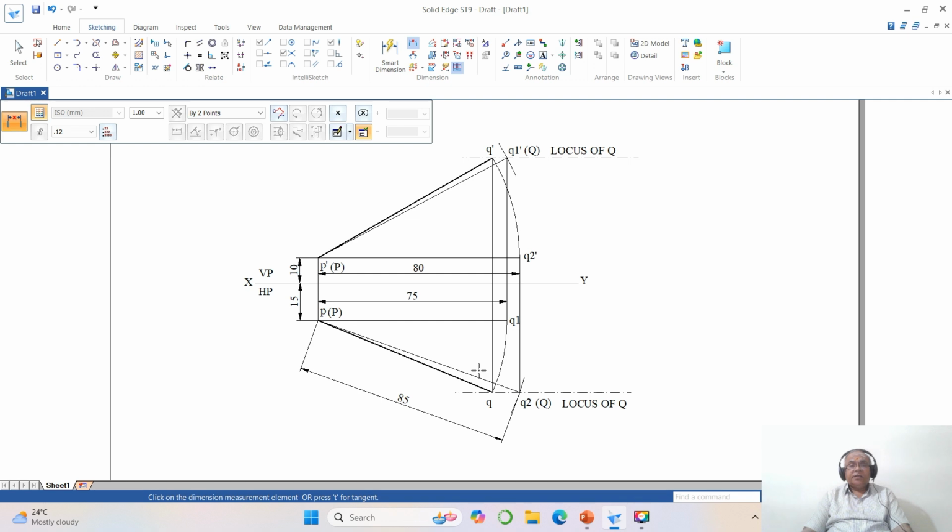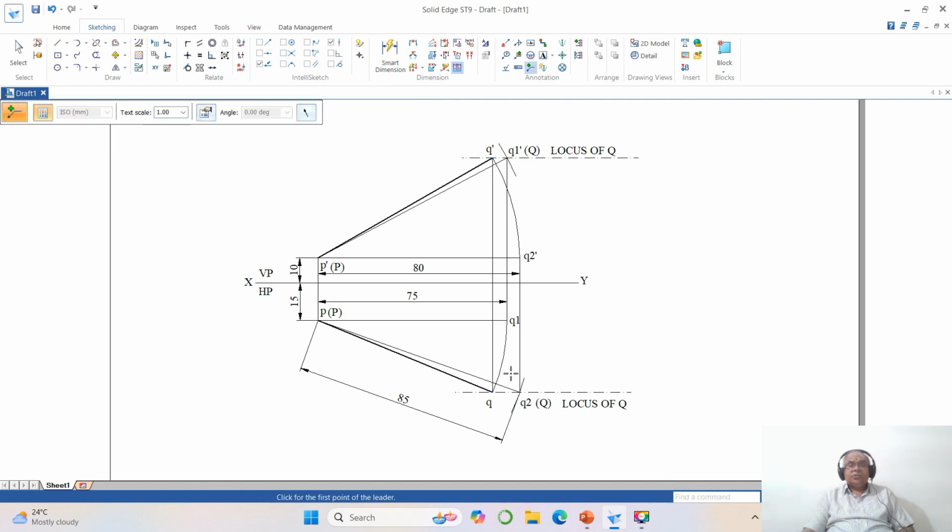So now we need to find the directions of projections. So to do that, here I will go for point on element, remove all these things. So go to leader. So you select this, then you select this. Similarly, you take the direction from here and then it comes down to this. So this is how you will be able to create the drawing.